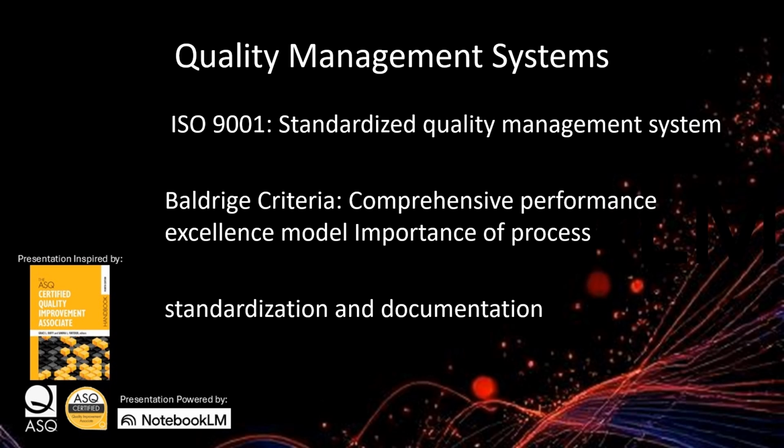Now let's talk about process capability. Process capability is about how well a process can consistently produce good output. You got it. It's a measure of how well a process can meet the specified requirements. So is it capable of meeting those customer expectations? Precisely. We often use the Process Capability Index, or CPK, to quantify process capability.